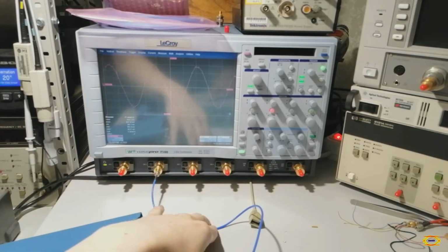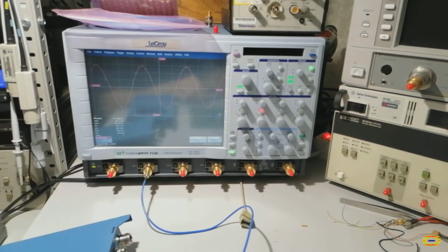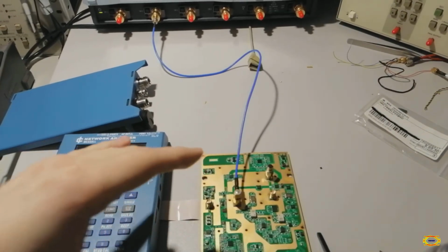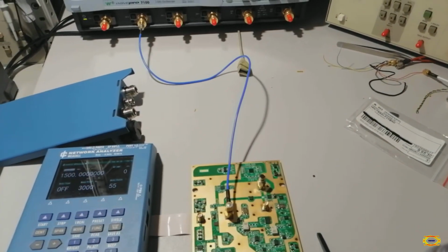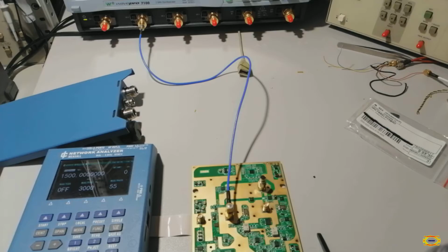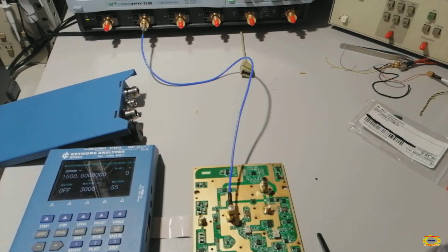We have a cable over there, some BNC SMA connection, and the VNA doesn't have to output exactly the level you set on the instrument, because the VNA doesn't actually care so much about output power. You have to measure some power relation between two ports or on one port.